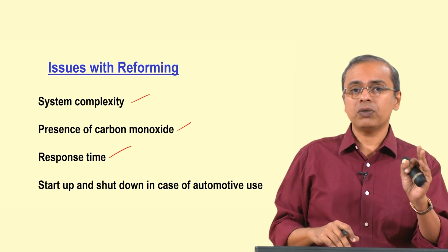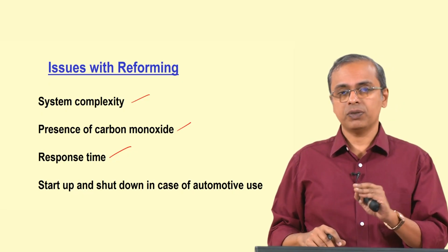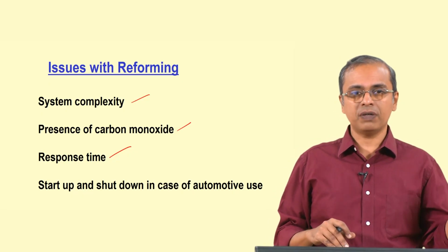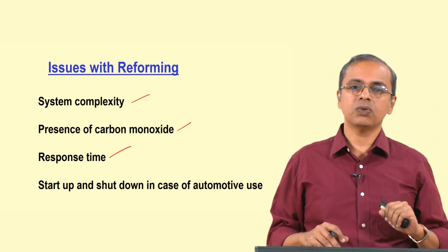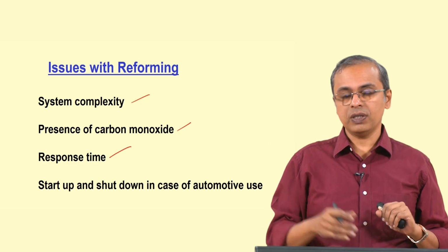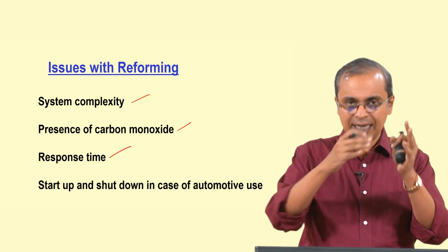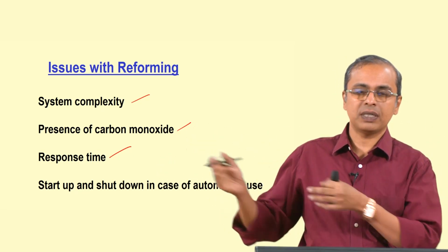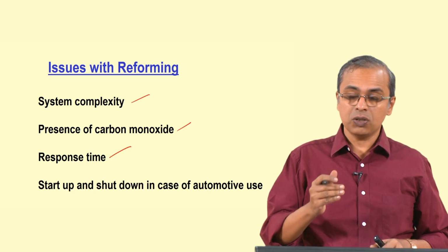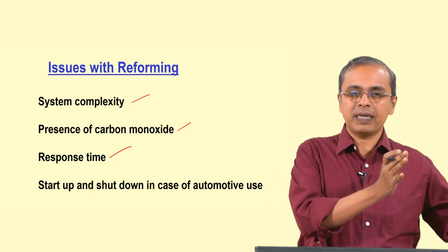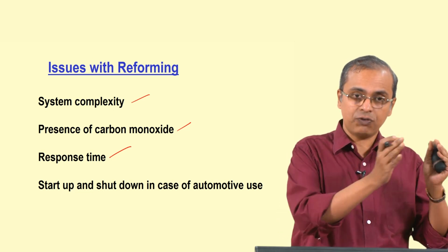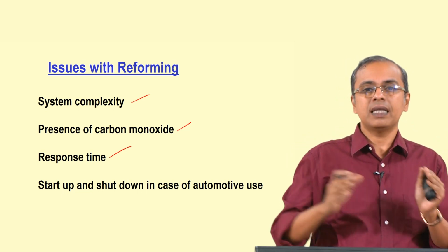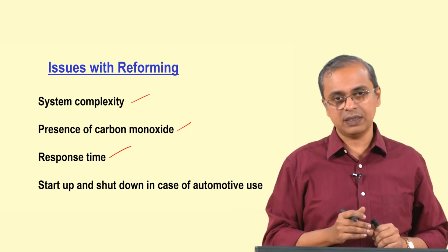But the reformer on the other hand may take several minutes. It may take several minutes for it to go from whatever was the previous setting to a value that is 10 times as high. You can suddenly increase the input, but it still takes some time to do all the processing and then send you an output that is now 10 times higher. So, the response time of your power source is much longer, and therefore a much slower response time than what you can do by just coming in and turning on switches.